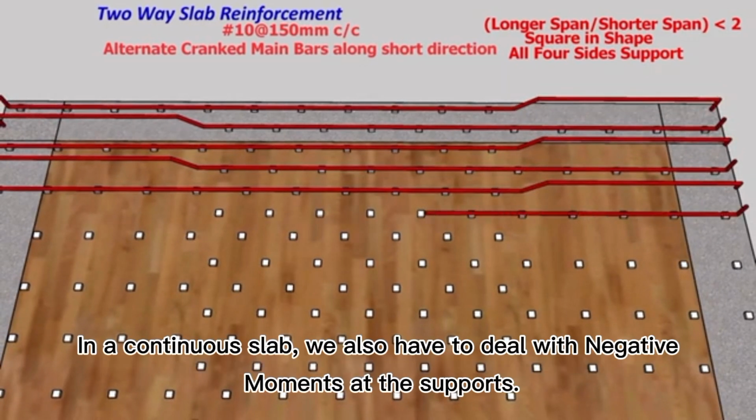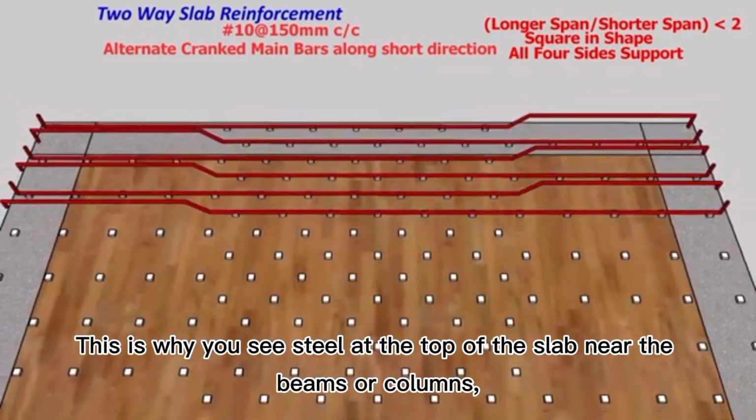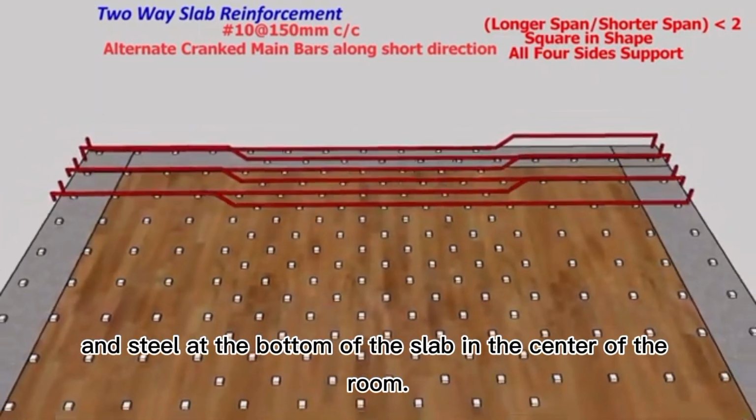In a continuous slab, we also have to deal with negative moments at the supports. This is why you see steel at the top of the slab, near the beams or columns, and steel at the bottom of the slab in the center of the room.